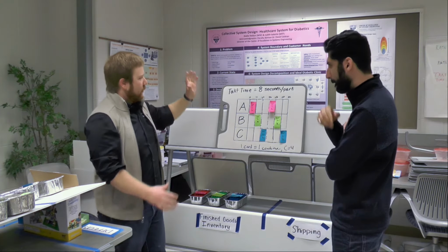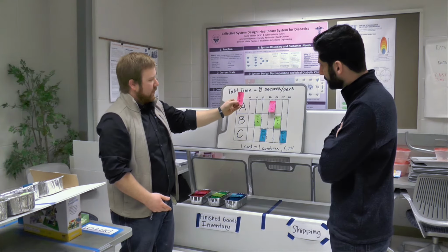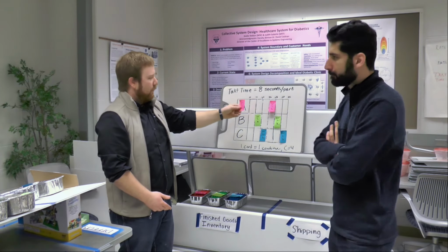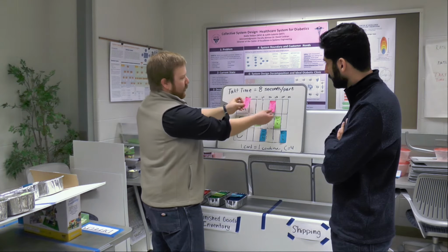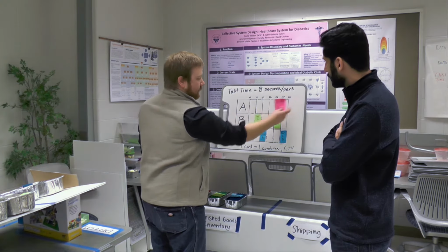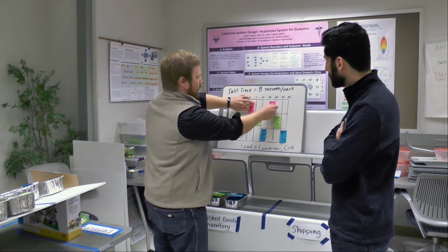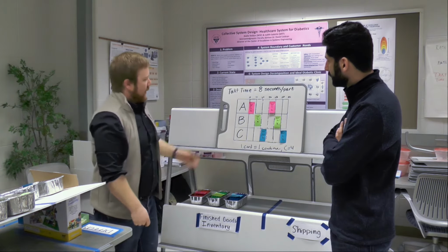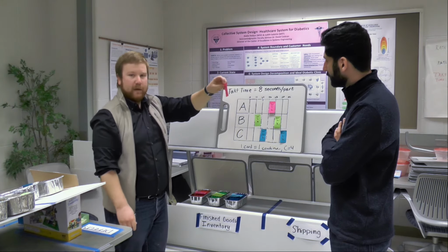On the Heijunka box, we have a withdrawal Kanban, and each of these cards represents a container of 4 parts. So to make my order at the end of the day, I'm going to have 4 red and 4 red, which gives me my 8 red, 8 green, and 8 blue. So at time 0, the timer will tell me, pull a withdrawal Kanban.